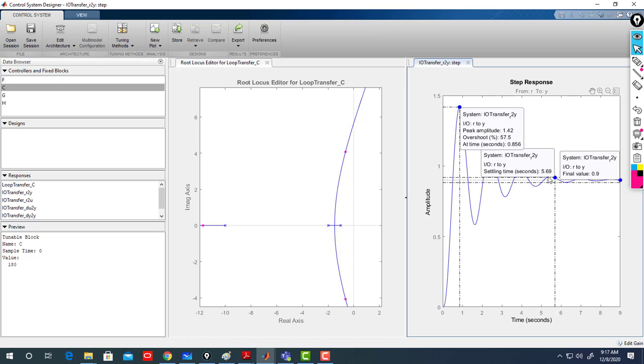So see, I don't want to affect the transient response. Now I add a compensator that doesn't affect the transient response, which is working at 57. So this is what they said. So the transient response currently is this one. So now adding this controller, the compensator, will reduce the steady state error to 0. So they will cancel the error. So you see it's 0.9 final value. So I have an error of 0.1 to reach the 1 step. So then adding this compensator, it reaches 1 without affecting the transient response.